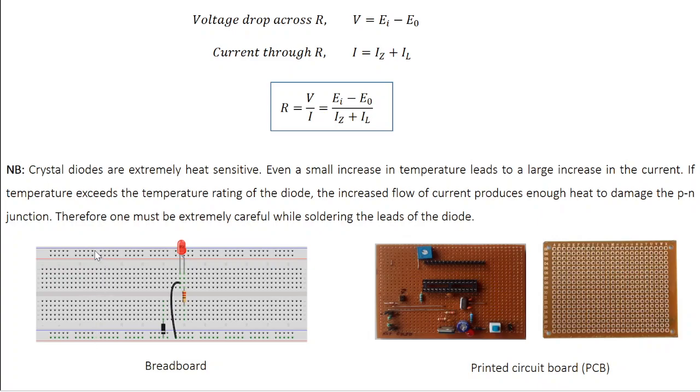these holes are horizontally connected, and when it comes to the center part, all these holes are vertically connected, so you do not have to solder the components. You simply insert the component, you insert the diode, you insert the wire, and the connection is internally done.